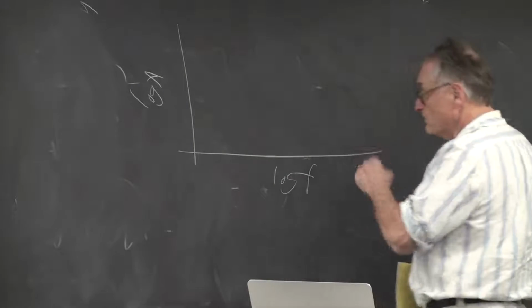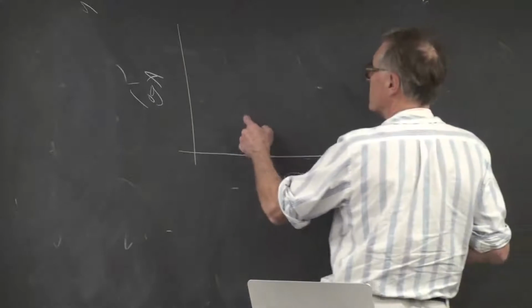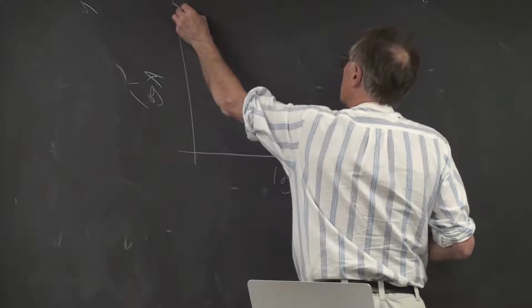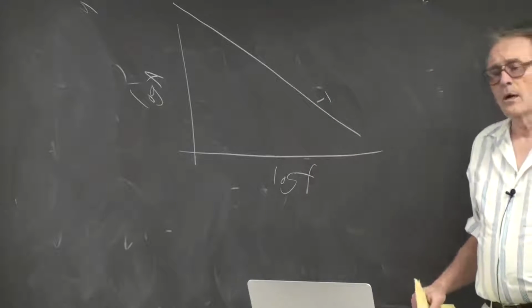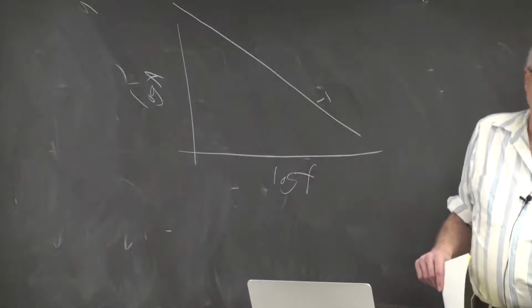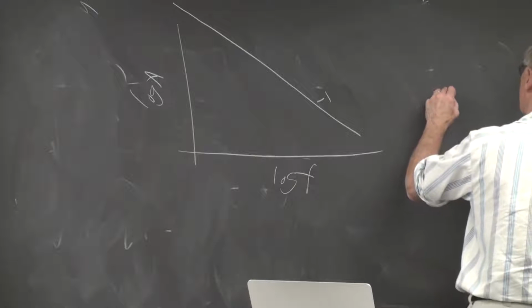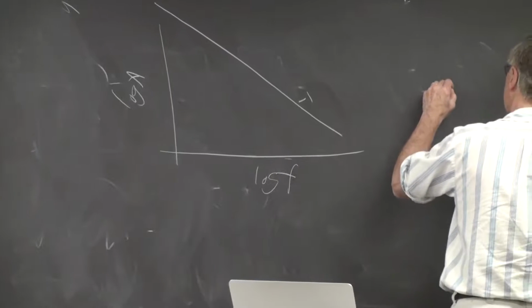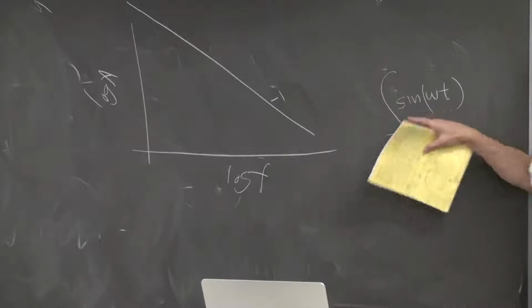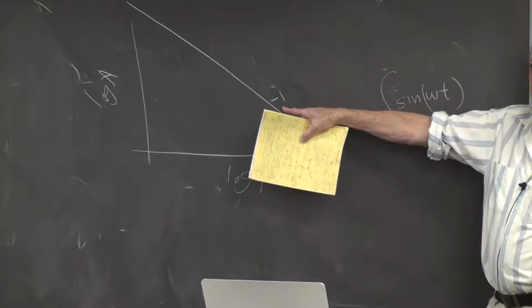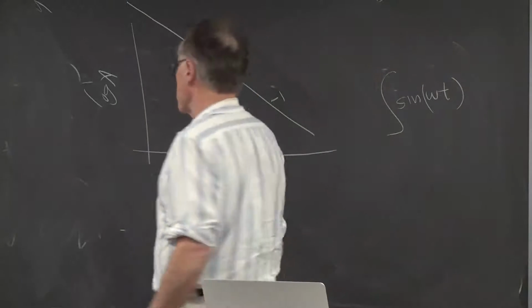So if we look at log A versus log F for an ideal integrator, it's got to start at infinite gain and drop forever with a slope of -1. Why is it -1? When you take the integral of sine omega t, you get a 1 over omega, corresponding to a slope of -1. So, ideal integrator.